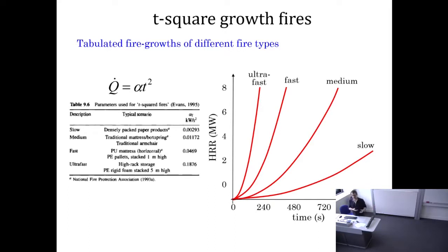Really, you put it into a test, and you have to show that the materials it is made of will ignite for sure, okay? But it will take too long to ignite. When it burns, the amount of fuel, the burning rate, is low, and the spread rate is small. And you do that either by playing with the amount of materials or by retarding the materials, which is this magic chemistry. It's literally magic chemistry. They put these really strong chemicals with very complex chemistry, but just tiny little amounts in your polymer matrix, and then the resulting behavior in fire is lower spread rate, lower heat of combustion and lower burning rate. And then it passes the test, and then IKEA can sell in the UK.